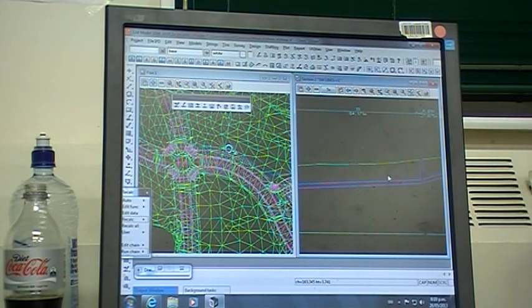If I need to update a stormwater system and go under an existing road, they won't let you open trench it without specific permission, and so you then have to comply with the minimum cover under a road. Yes, that brings in a whole different set of design thoughts and processes.